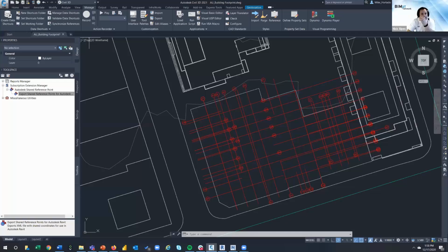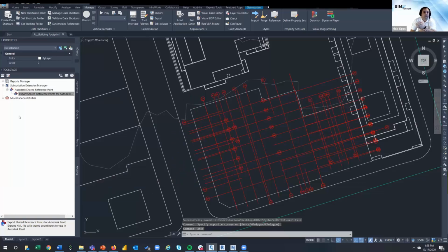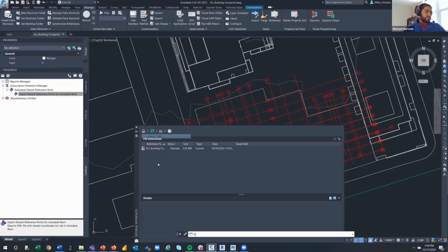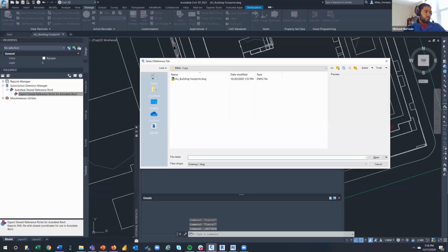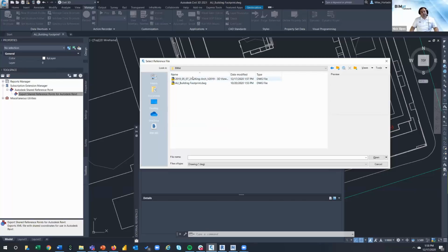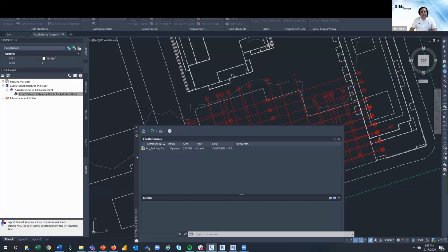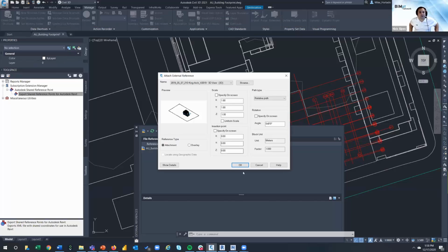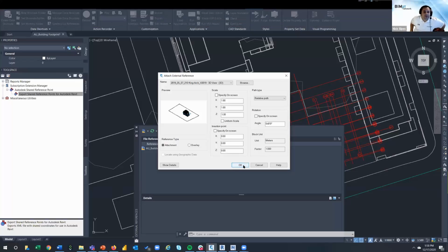Yeah, the only issue that, the other, I don't want to say issue. The other solution you have is you can also use a Navisworks file, which is a little bit smaller on the AutoCAD side of things, as far as working with it. Because DWGs and Navisworks files are the only files that you can export from Revit and use shared coordinates. Everything else exports with project coordinates or internal coordinates.